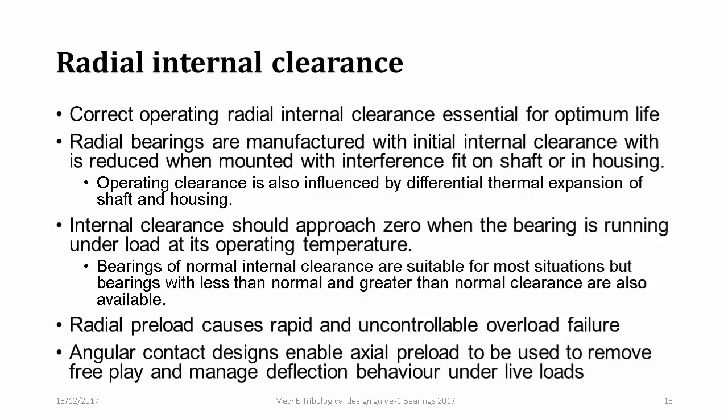Radial preload needs to be avoided at all costs. It will cause rapid and uncontrollable overload failure. The way around this is to use angular contact designs where the contact angle in the bearing is not zero, but anywhere between typically 20 and 40 degrees. And I'll show you in a few minutes how we can use that construction to eliminate play but still manage the deflection behavior without this sort of runaway overload.